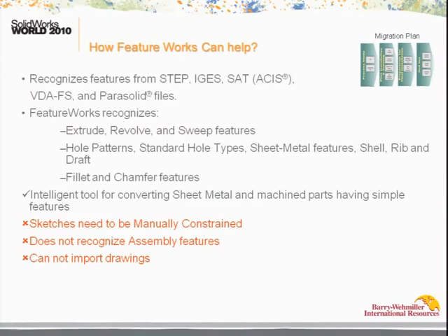If you try using an automated tool, if you try using something like FeatureWorks, what it does, it brings in the base geometry as a dumb model and adds some features like maybe chamfers or holes or extrudes, or all those stuff. Those are added on top of the dumb imported geometry. But that is not really what you want to do, because you are losing out all the parametric information in the base model which is coming in.